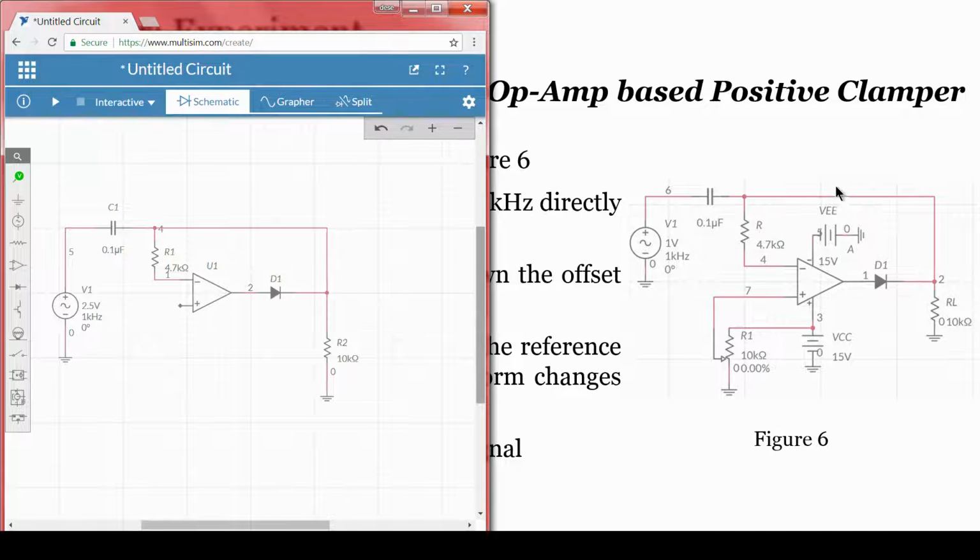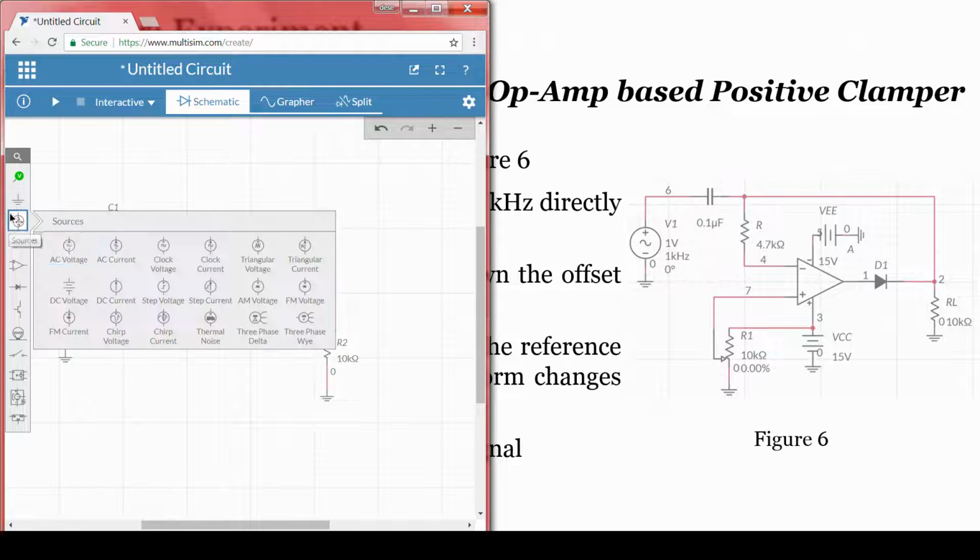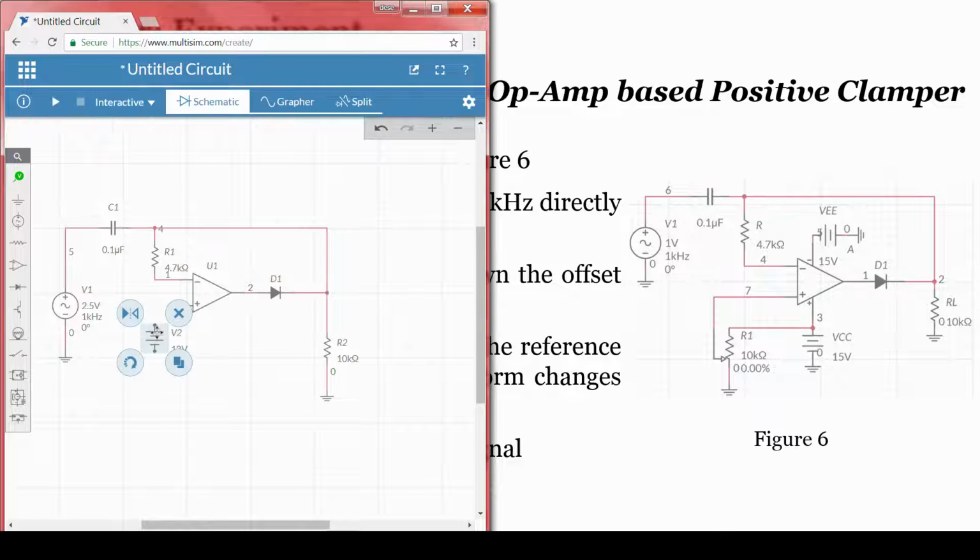If you look into the circuit carefully, we are providing the reference voltage using a potentiometer. The positive terminal is connected to the potentiometer, and by using the wiper we are giving an input to the non-inverting terminal. Rather than using a potentiometer, even in this case I will take a DC voltage and connect the input DC voltage to the non-inverting terminal. As a result, it is nothing but some particular reference we are providing, so it will act as a reference to the circuit.